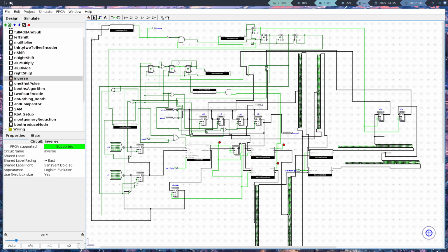And this had a lot of challenges. I think the first big challenge I had was trying to figure out how to get these registers to update themselves, right? The first instance was fine. The first instance of the Euclidean algorithm was okay. It was the general case that was a pain to implement. And the way I solved that is I realized that I can actually nest these finite state machines together. And that was the big aha moment. That makes sense. It gave me the amount of granularity that I needed to control this circuit and get everything to time themselves properly.